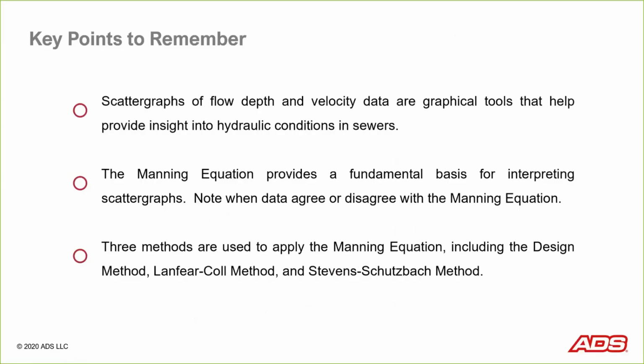And that occurs, to be honest with you, whether you plot the Manning equation on the scattergraph or whether you just implicitly visualize it on there while you're looking at the data. And what you're really looking for is when the data agree or disagree with the Manning equation. And then when it comes to using the Manning equation on the scattergraph, there's three methods in which it can be used. One is the design method. That's the one most of us are familiar with. And then if we have data and we want to curve fit the Manning equation to data, there's two approaches that we can use, the Lanfear-Cole method and the Stevens-Schutzbach method.